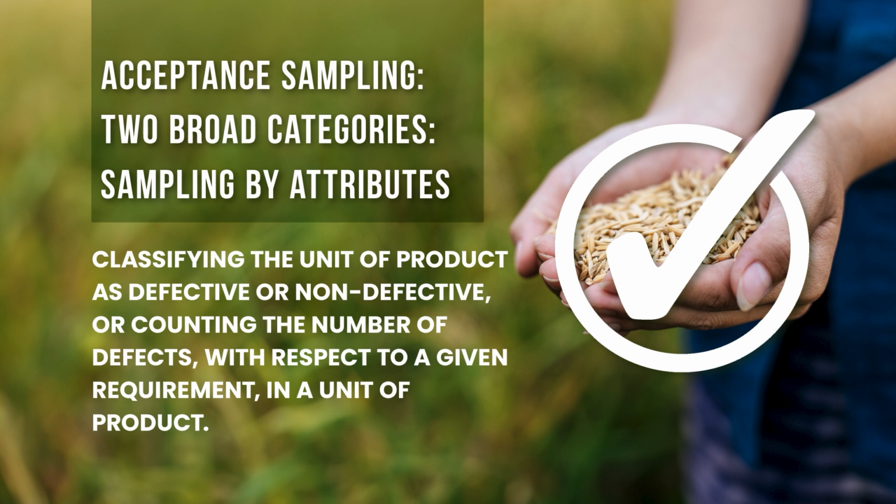It has to be less than 2. So if 2 samples are scratched or broken, the inspector will reject the consignment. Accept the lot if the number of rejects is less than the predetermined number. For a product sold in lots of 1000 kg, as I have told you, if you have drawn 50 samples from 1000 items and 2 samples are broken, then the whole lot will be rejected.